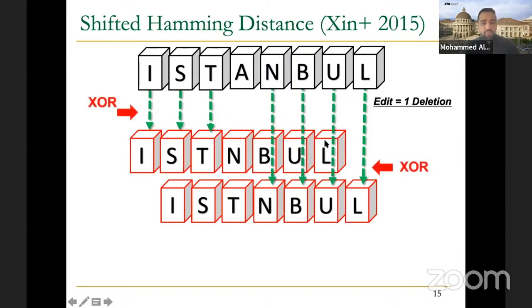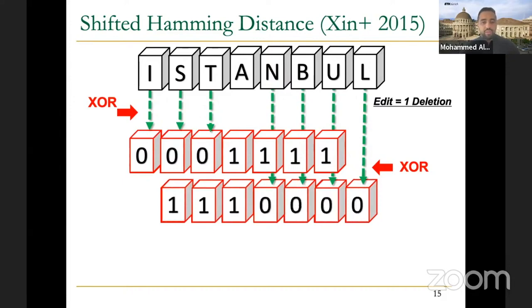So we have 3 here and we have 4 there. How can we do this in algorithm or in hardware? The match operation, we can do it directly using XOR, right? And now this is the XOR result. If you convert the match into 0, because there is no difference. In an XOR operation, if the number of differences is odd, then you always get 1, right? But since here they are always the same number of characters, T and T, then that is even, not odd. That's why you got the 0 over there.